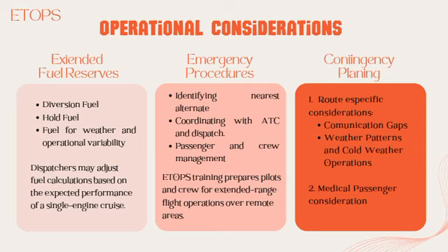First, the communication gaps. Some remote areas have limited communication coverage. ETOPS planning includes checking for radio frequencies or satellite communication links to ensure constant contact with ATC.